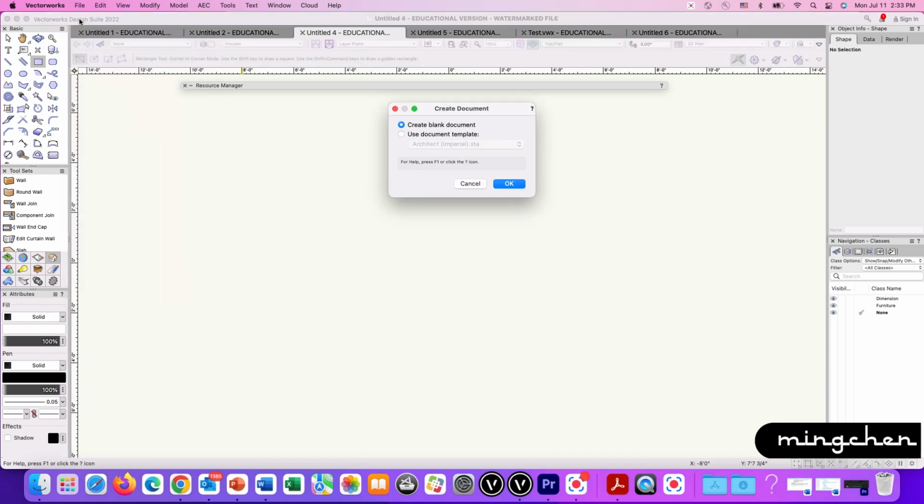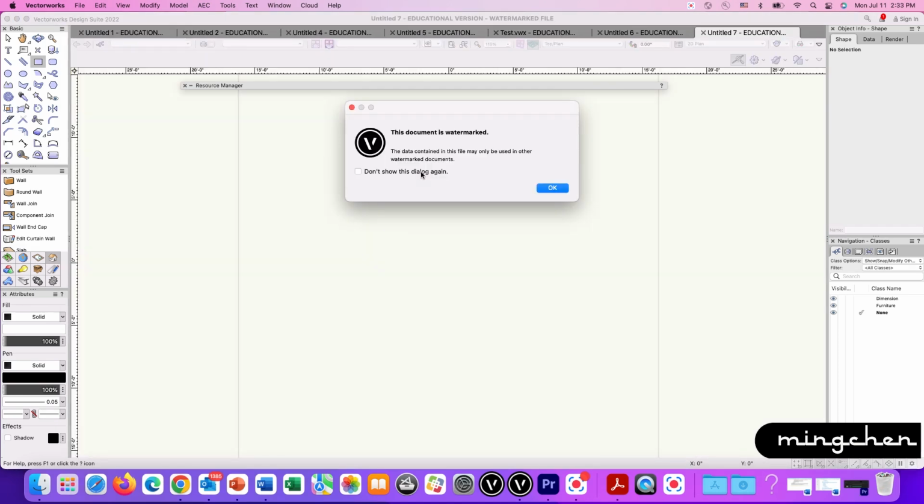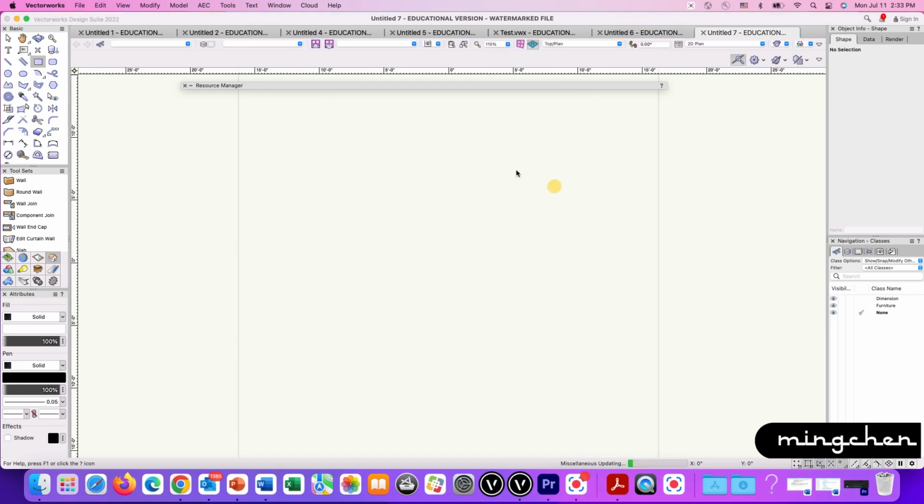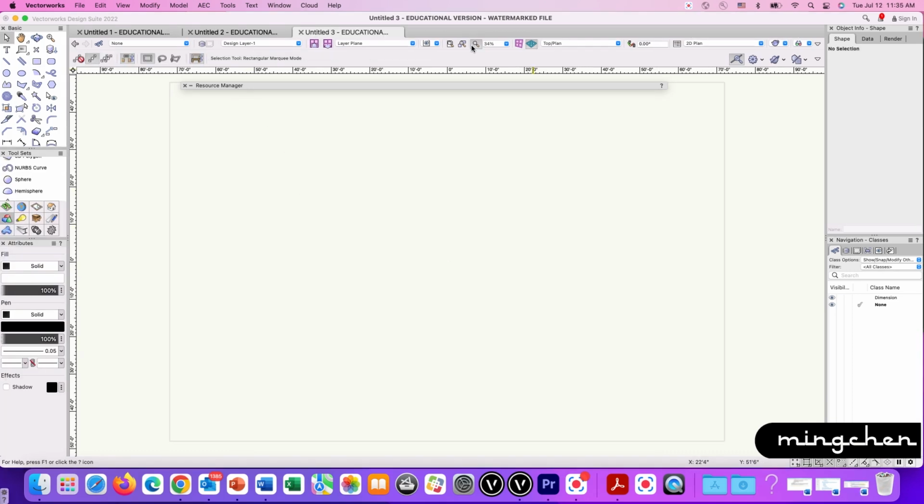After you have downloaded the VW software on your computer and opened the file for the first time, the application window shows you a default setting with frequently used tools and commands in an open position and arranged logically. The bars are located on the top of the drawing area. Those include top menu bar, the first line, Vectorworks version bar, the second line, file name type bar, the third line, view bar, the fourth line, and tool mode bar, the fifth line.